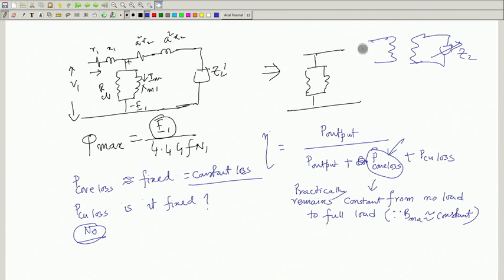Here it is V1, f1, that is fine. Open circuit, Z2 is infinity, the switch is open. Then I will load it by decreasing this Z2 and your current will go on increasing, and the ratio of the currents is approximately the turns ratio. Therefore, the level of current will go on changing as you change the load on the secondary of the transformer.